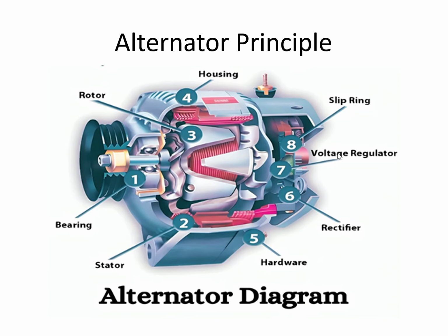The voltage regulator is used to make the voltage produced by the alternator be maintained constant, because sometimes the speed may be somewhat varied in the rotation side. When the speed changes, your output voltage of the alternator will also get changed. To avoid that, to make the voltage constant from the alternator, we are using this voltage regulator.